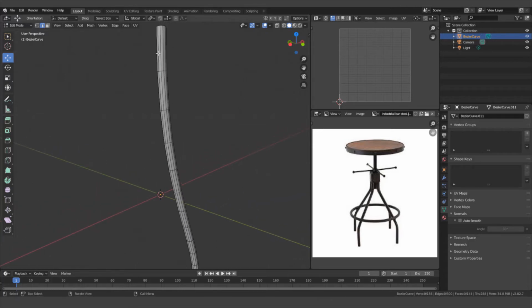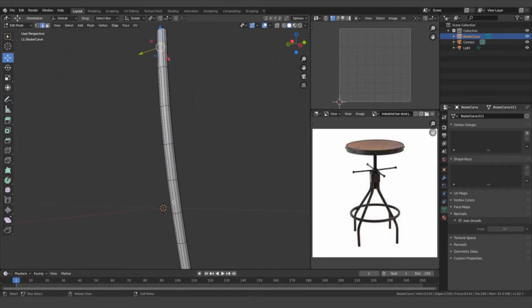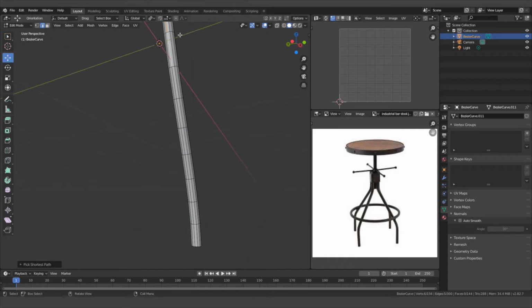So I'm going to grab this edge by left clicking, and then I'm just going to go down as far as I can and control left click. And we can see that Control Z, it messed that up. So I'm going to just come down here. So just control and left click all the way down the object, and you'll see. And you saw the mistake that I made, I was slightly off, and then it's going to try to go the shortest distance between those 2 points. And if you're off one side or the other, you saw what happened there.